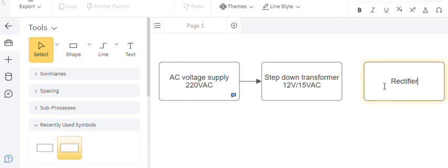I have explained to you using those graphs that what the rectifier does is to cut off the negative side. And if you are using half wave, it's only going to cut off the negative side and we are going to have blanks, blind spot. Did you remember that? But if you are using full wave rectifier, there is not going to be blind spot. Throughout the life cycle of the voltage supply, we are going to have voltage, constant voltage. However, it will be reducing and increasing because of the wave. But the next mission here after rectification stage is to remove that wave.